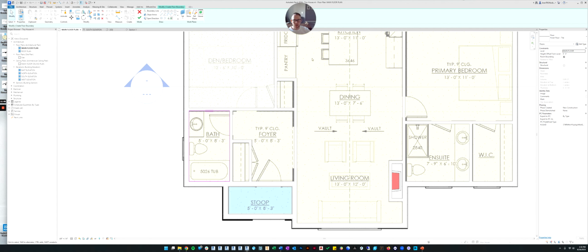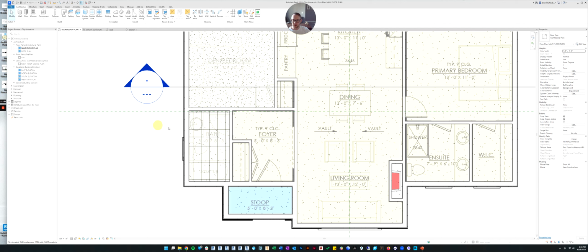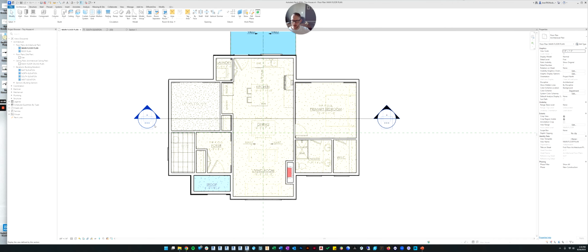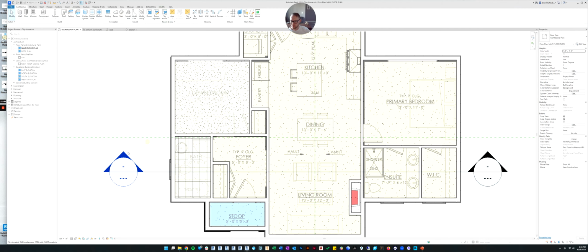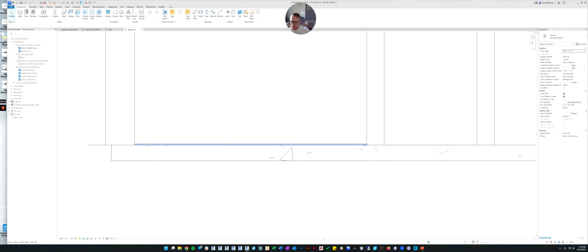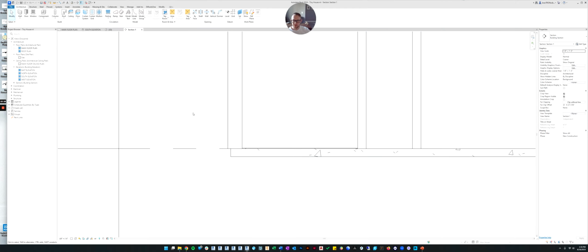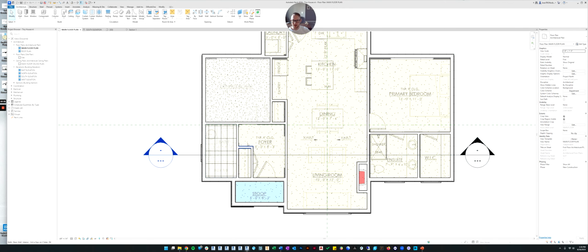And now we're back to our sketch. So let's finish our sketch. And again, we forgot to offset it. So it's giving us an error that they're running into each other. So let's select the tile floor again. And remember, let's put the 1/4 inch offset, and then it'll move it back up. If we want to check to make sure we did it right, we can take this section and move it into the bathroom and then look at it. And you can see when we select it, there's our finished floor tile and it's sitting on top. So if we go back to the main floor, now we have our tile floor.